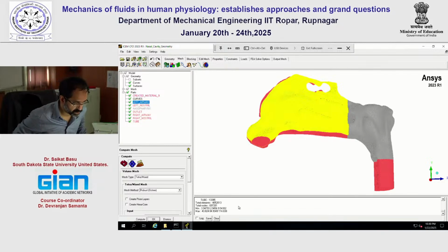So for example, this simulation, if I run it, it probably takes a day at most. But the full airway simulation with the 13 million elements, the computer was not doing as well, but it took me around 11 days. So it's a function of that. So it's the time cost prohibitiveness that you need to think about. But 4 million is fine for this one.